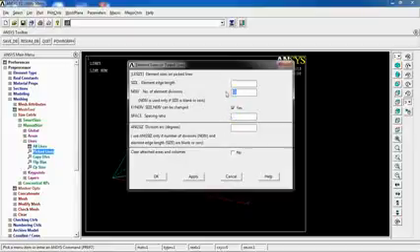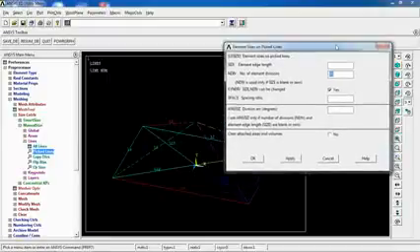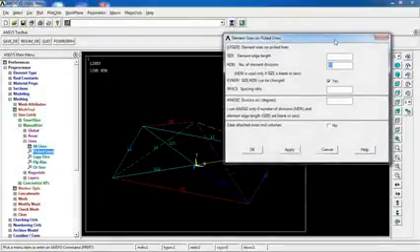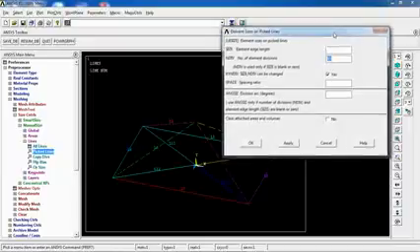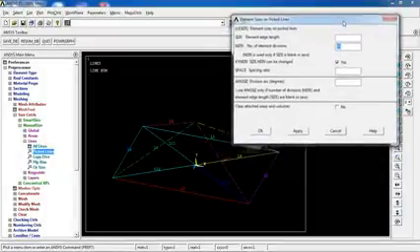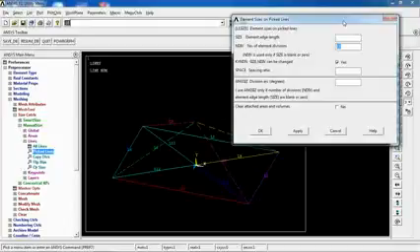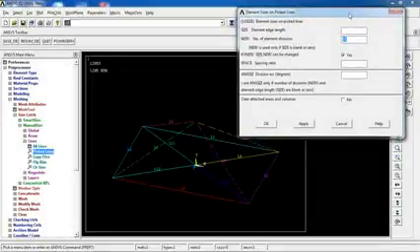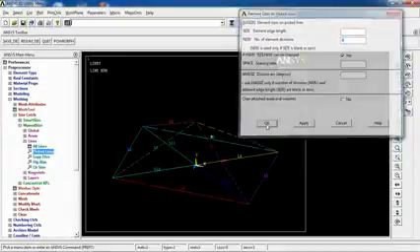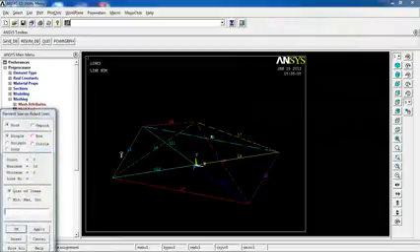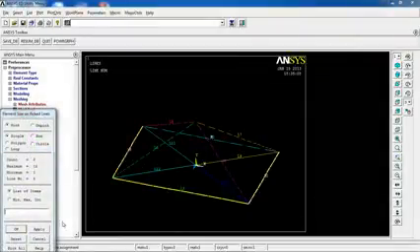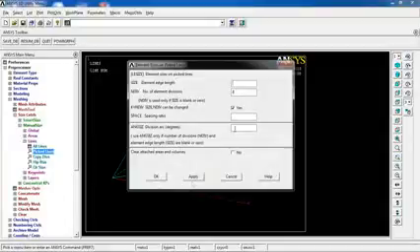divide that into, let's say, 8 segments, because the reason I'm doing this is I'm a little bit cautious in here, so that the number of meshes, the number of elements that I will get after meshing will not go above 10,000, so that my ANSYS will face an error. So I'm just dividing that line into 8 segments, and also I'm going to do the same thing with these lines. 8 equal segments,